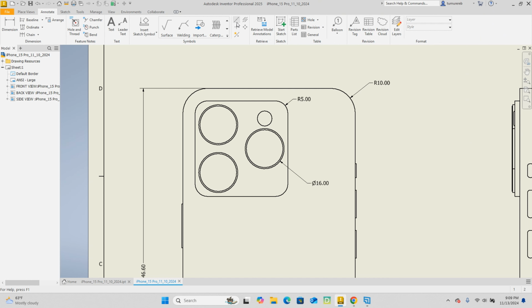Let's select center line. Find the center. How do we know the center? Green dot. Awesome. Left click again and then right click to clear. If you forget to right click and clear, it's not going to work.